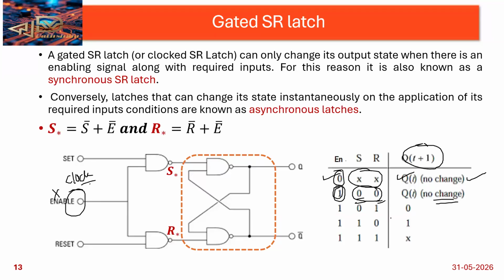In general terms, not with respect to the truth table: when do we use a latch and when do we use a flip flop? How do I understand whether I have to use a latch or a flip flop? Suppose in each and every circuit there is a clock signal, then we will use flip flops. Latches are also storage elements. Suppose I want to use an enable pin, then I do not depend upon the clock, either positive edge or negative edge. So I don't want to use the clock, I want to use it as a switch.